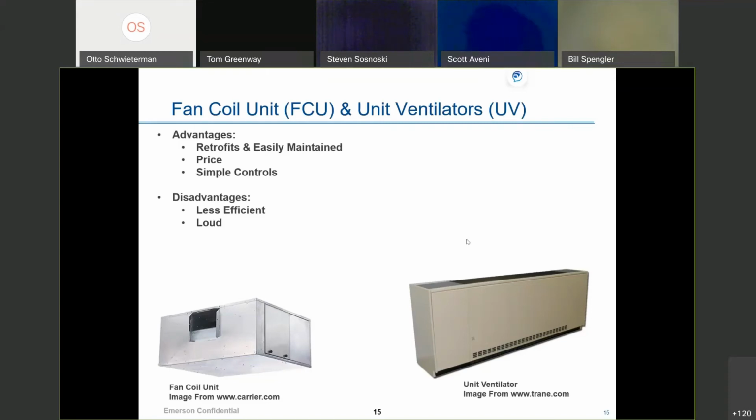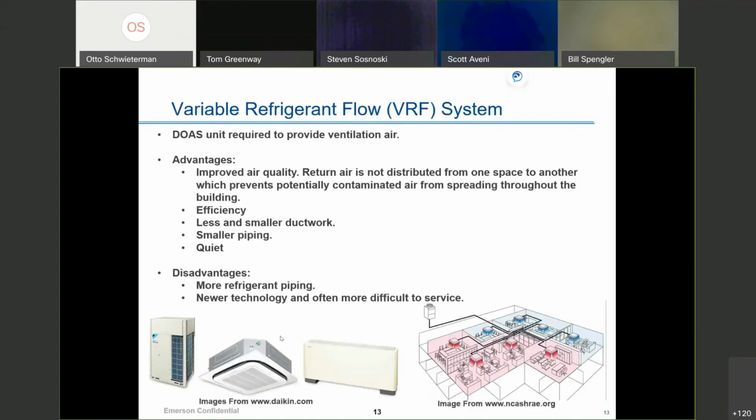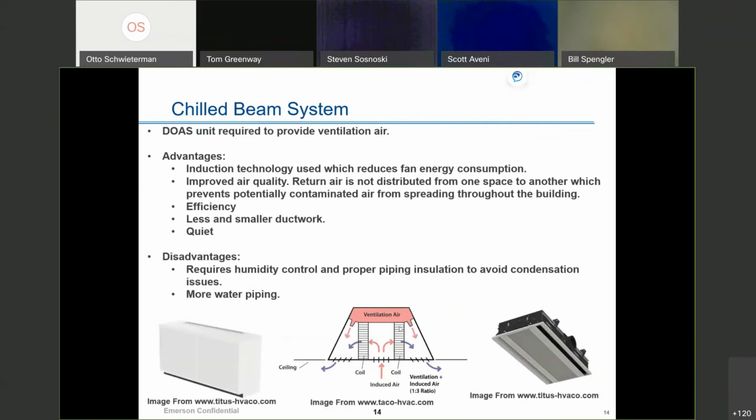I think Tony asked a question about how these are different from VRF systems. The VRF systems are not going to have these ducted. They are going to have inside units right here, but instead of having hot or chilled water come to these spaces, they're going to have refrigerant come into these terminal units, and the VRF system can do simultaneous heating and cooling as well, which makes it more efficient than what... at the same time, which is part of the reason why they're less efficient than a VRF system.